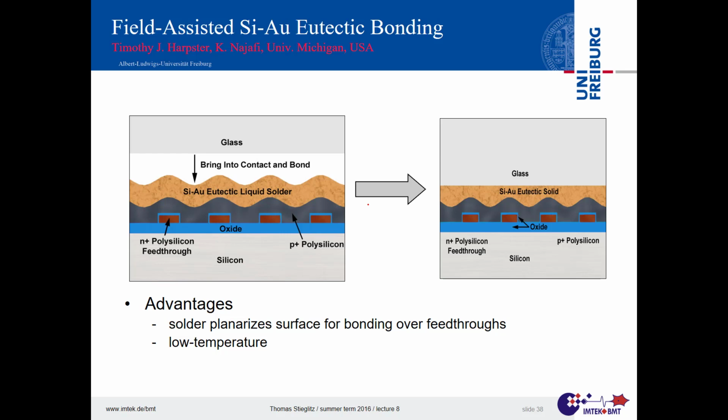This gold diffuses into your electronic components and has a lifetime doping, so it sits down immediately at the Fermi level in the band gap, and with that all of your transfer behavior of electronic circuits is completely distorted.